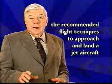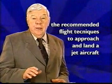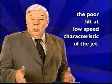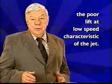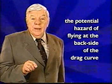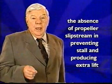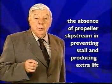We have come to a point in our presentation where we have gathered fair knowledge to give a full treatment to one of the end products of this video, the recommended flight techniques to approach and land a jet aircraft. Just to recall what we have said till now, a jet may be worse than a propeller aircraft in the following ways: the poor acceleration response of the jets in low engine rotation, the poor lift at low speed characteristic of the jet, the potential hazard of flying at the backside of the drag curve, the absence of propeller slipstream in preventing stall and producing extra lift.